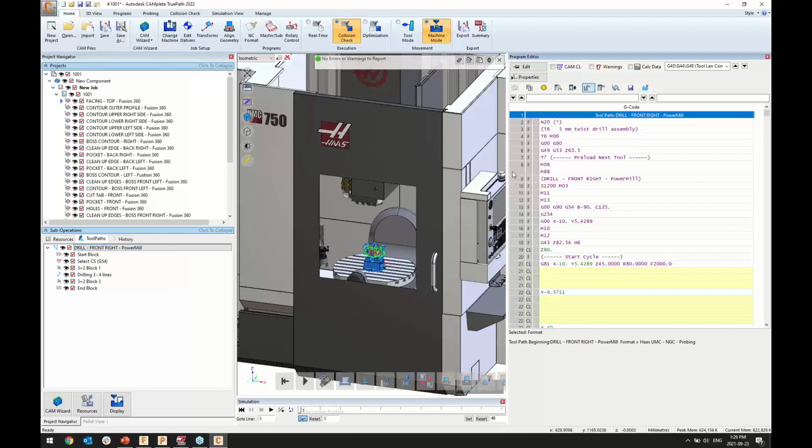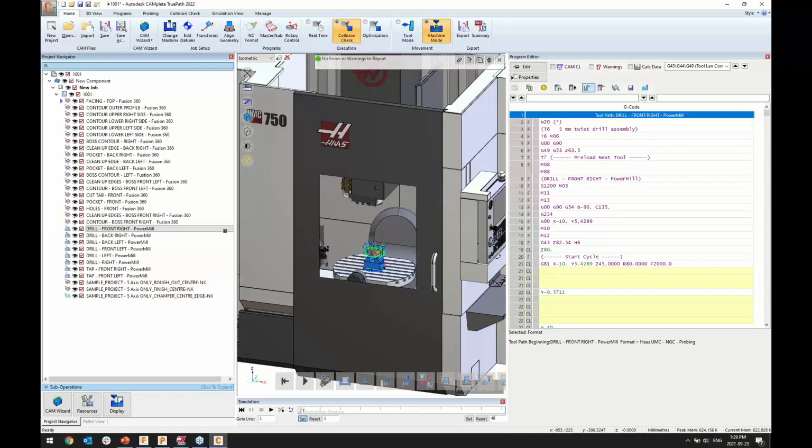And ultimately, that particular toolpath is now going to produce a particular G-code output. So all of those elements will be able to be controlled independently from each other or as a whole, as a process altogether. The next step at that point, now that we have the code, will really be validating this code. Can the machine tool, with its own limitations, generate and run this toolpath without creating any particular issue?